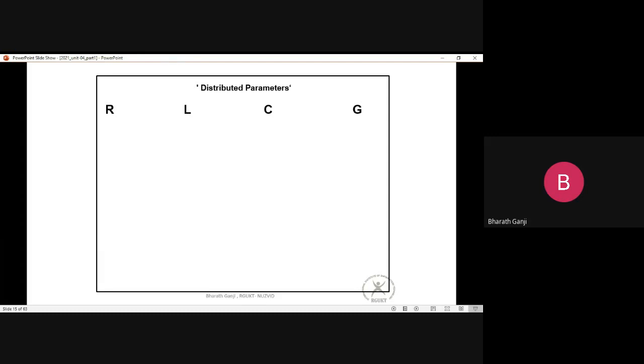Of course, the delay you can model with an inductor and a capacitance, but on a line, usually lines are not lossless, they can be lossy also. So you can have resistance on your lines, which can actually decrease the values of the potential also. So you don't assume that the resistance is only at one location on the wire. Okay, if I take a copper wire, I'm no longer saying that the resistance is only in this region. Resistance is not a lumped effect at one place.